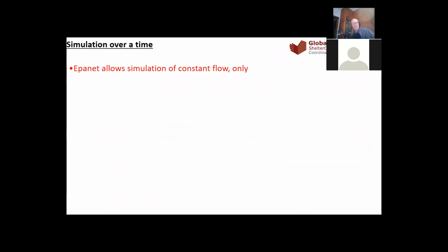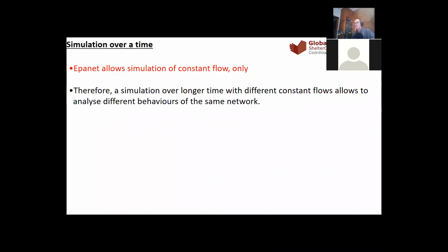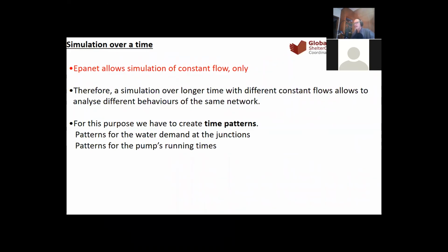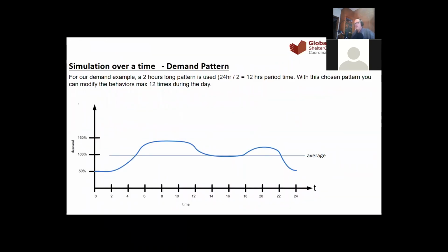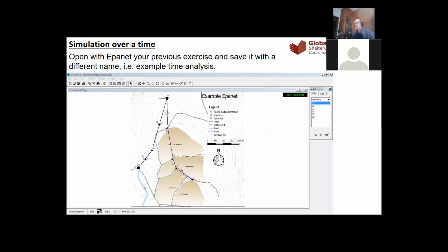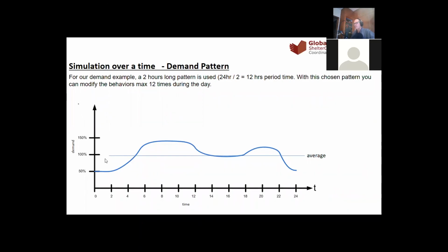Like I told you last week, Epanet allows only simulation of constant flow. That's why we make several different constant flows and we put them together. And these several different constant flows are linked to the time pattern. And it looks like that.